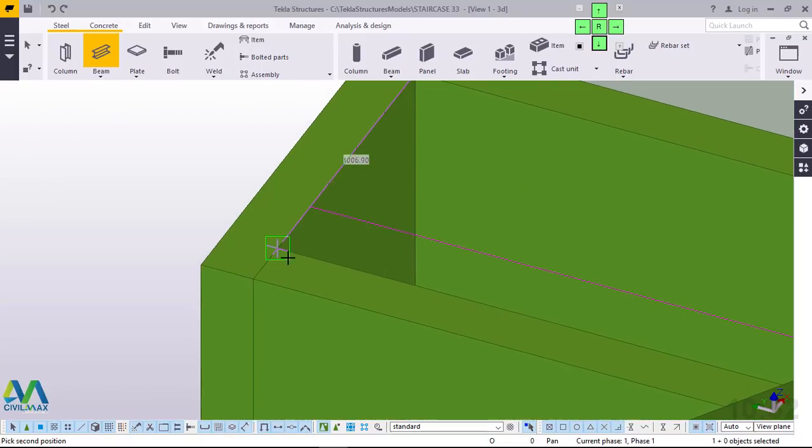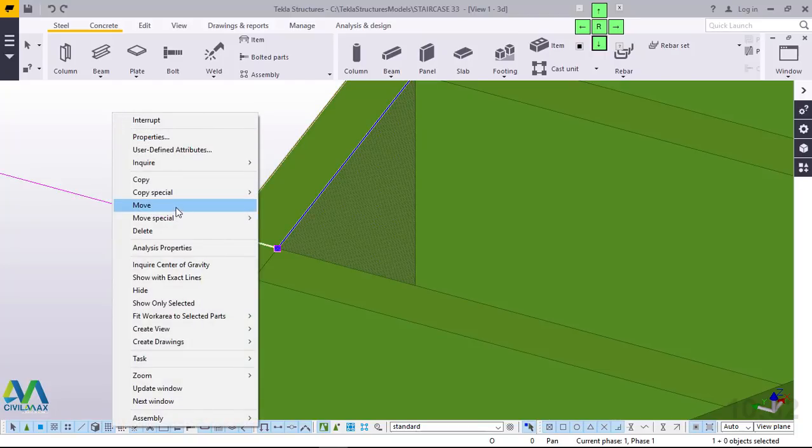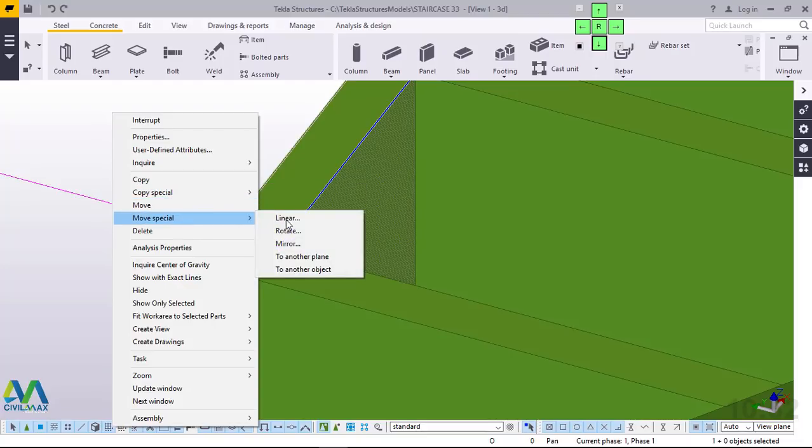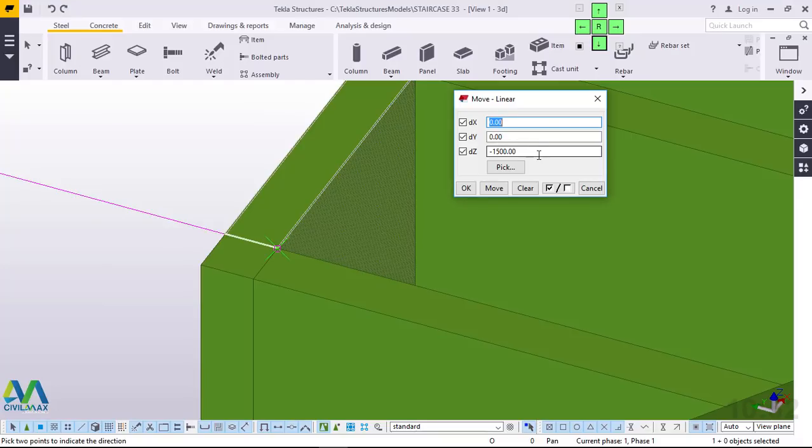Run all the way to this end. I'll snap right here. Right click, and what we've done can be seen. Just click on this and give it an offset of 50 millimeter. Right click and give it an offset of 50 millimeter. Now we'll just give it a move command. Click on that. Then we'll change the Z axis to 0.